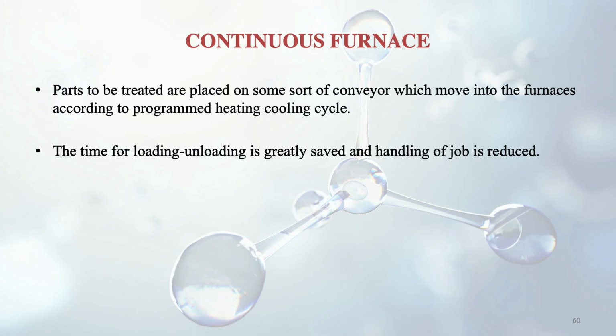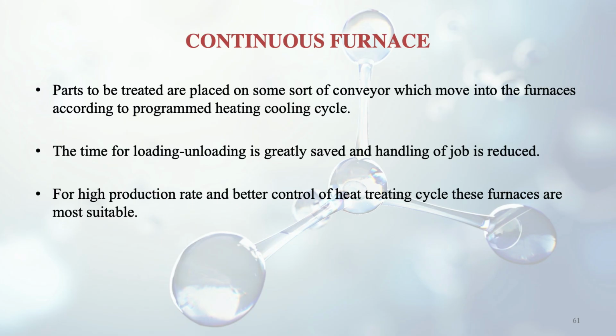The time for loading unloading is greatly saved in this case because it's continuous type, and the handling of the job is also reduced. So these are the advantages of this continuous furnace. So we are saving time here. For high production rate and better control of the heat treating cycle, these furnaces are most suitable. Obviously, if it is a continuous process, we will have a high production and we can control the heat treating cycle also in a much better fashion.